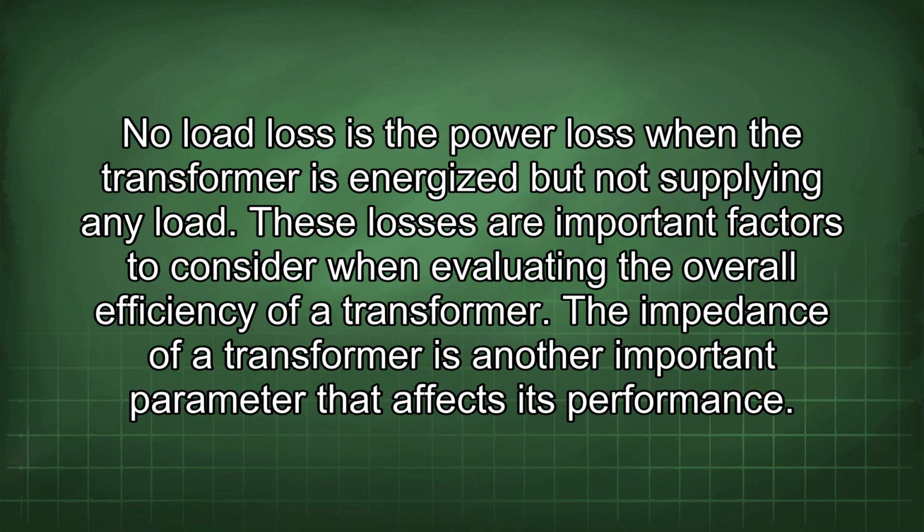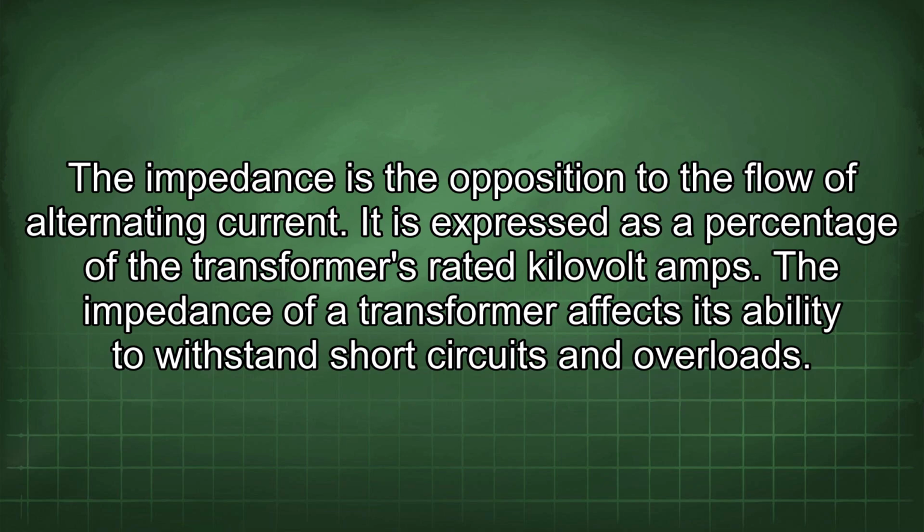The impedance of a transformer is another important parameter that affects its performance. The impedance is the opposition to the flow of alternating current. It is expressed as a percentage of the transformer's rated kilovolt amps. The impedance of a transformer affects its ability to withstand short circuits and overloads.